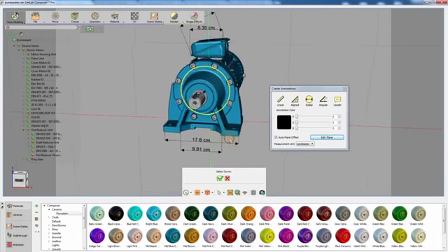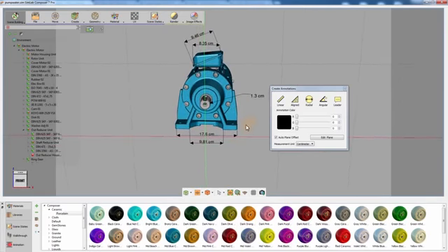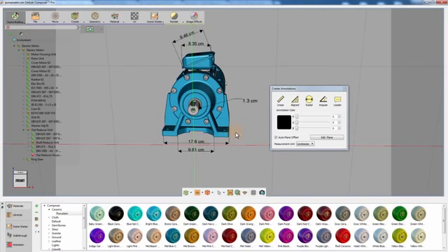Select the Radial Dimension tool and click on the edge of the rotating rod to measure its radius. Click again to set the length of the annotations indicator, and by moving the cursor, determine the length and orientation of the measurements text. You can change the measurement unit used from the Annotation dialog box. Select a measurement unit that is suitable for your design, and since this mechanical design is relatively small, setting it to centimeters would be fine.